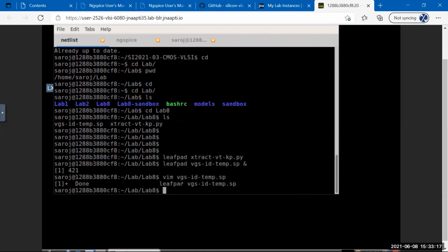For the Python one, actually Mike has the code written such a way that you can run the ngSpice simulation from the Python, but we are not using CppSim right now. He has his own tool called CppSim and everything happens through CppSim. So we'll not run it from Python. We'll actually run the ngSpice, create the data, and then we'll read it in Python and do all the post-processing. That's the way we're going to do it.